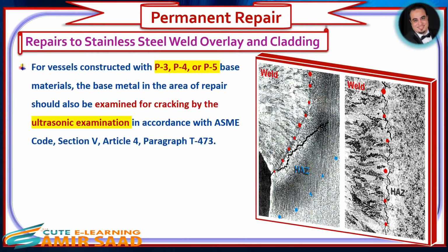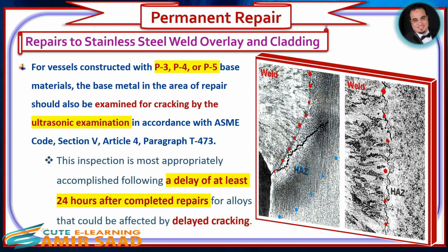For vessels constructed with P3, P4, or P5 base materials, the base metal in the area of repair should also be examined for cracking by the ultrasonic examination in accordance with ASME Code, Section 5, Article 4, Paragraph T-473. This inspection is most appropriately accomplished following a delay of at least 24 hours after completed repairs for alloys that could be affected by delayed cracking.